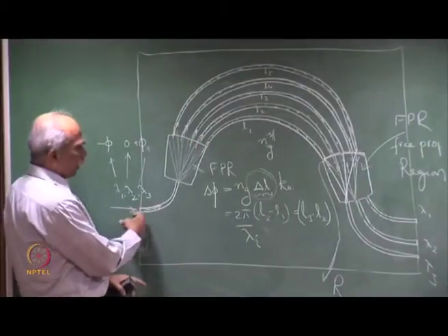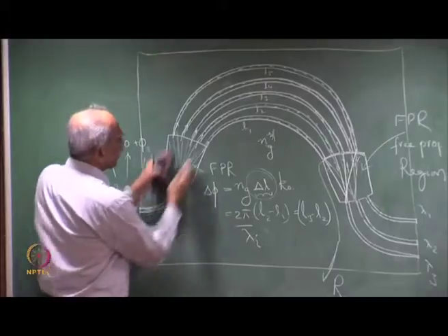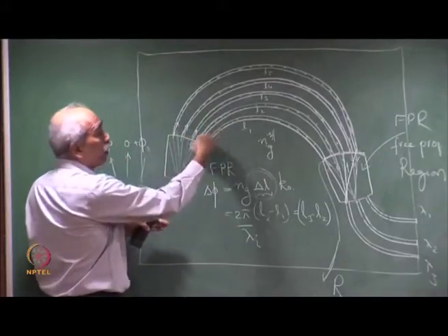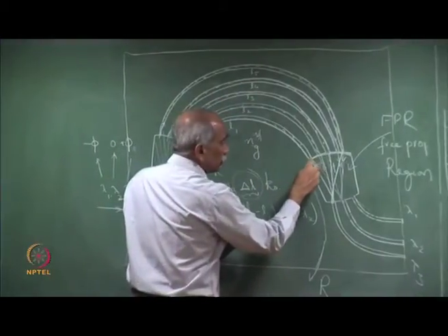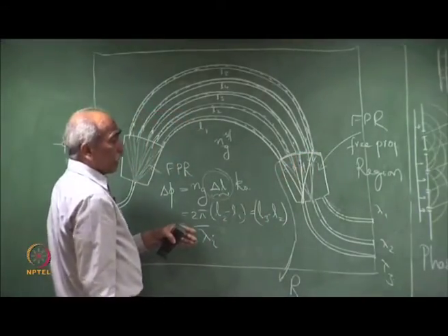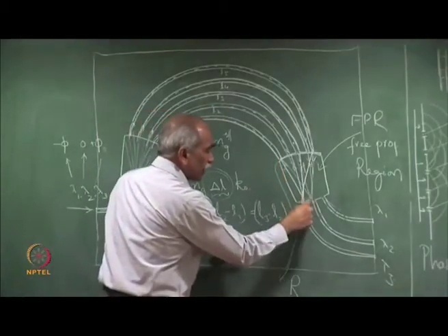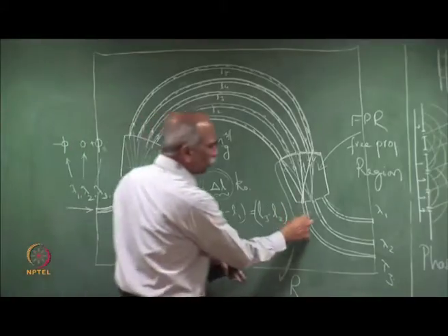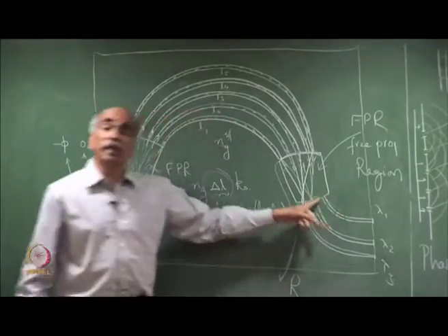So, the input here enters the free propagation region and diffracts. All the waveguides are carrying all the wavelengths. Different wavelengths have different phase shifts and therefore, the accumulated phase is different and therefore, they focus at different points. The output waveguides are then located at the appropriate positions.